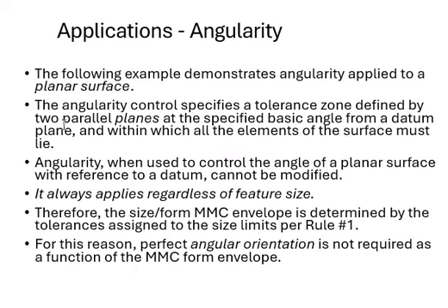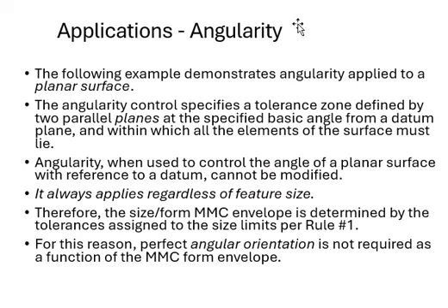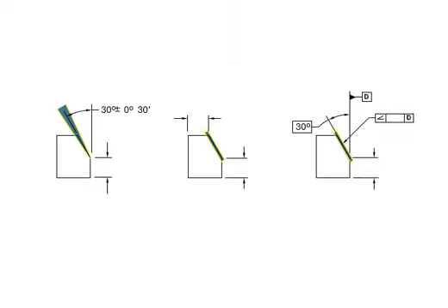Parallel zones are identified right here, two parallel planes, so it's this one we're talking about, and of course it's the same angle anyway. But then when we do this, of course the angularity, and we want to show how the angularity control specifies that zone, we put the leader line. That leader line is not here, that leader line is right there, see, very clearly.